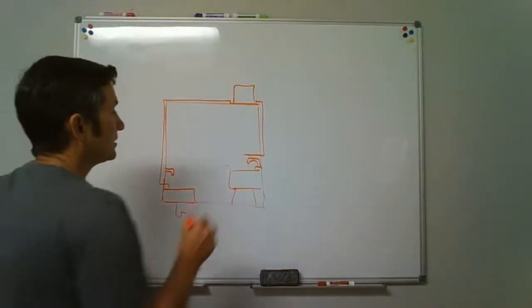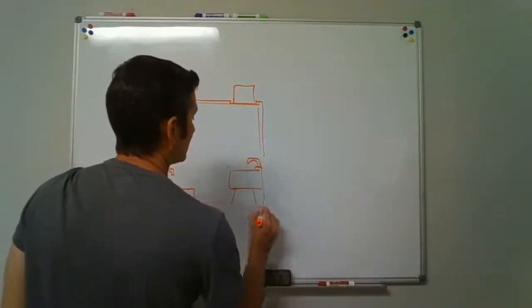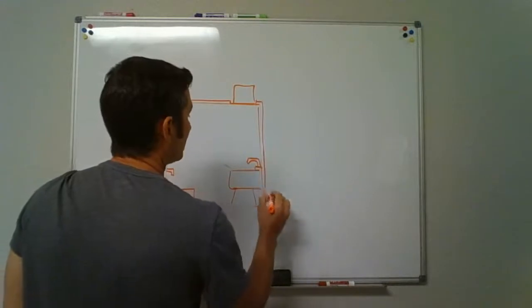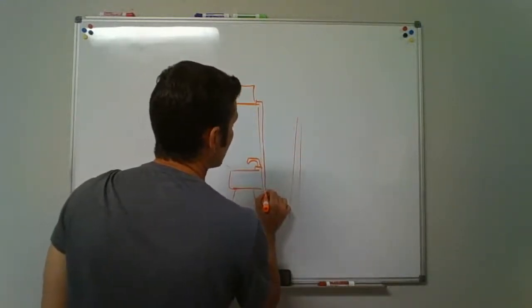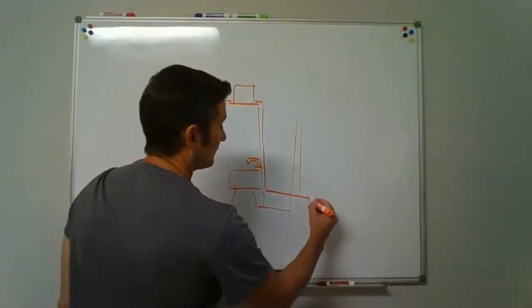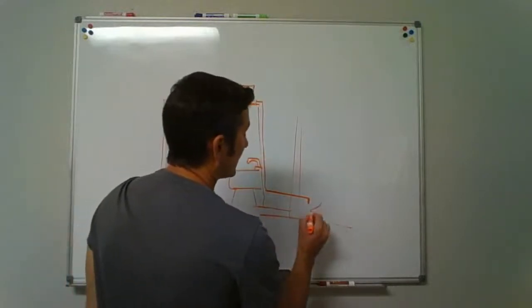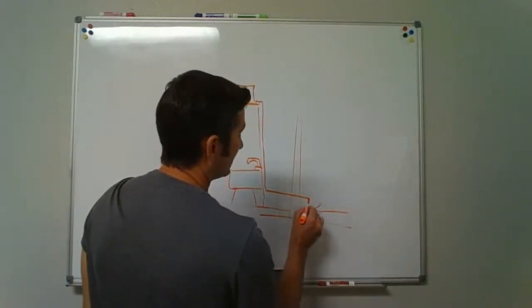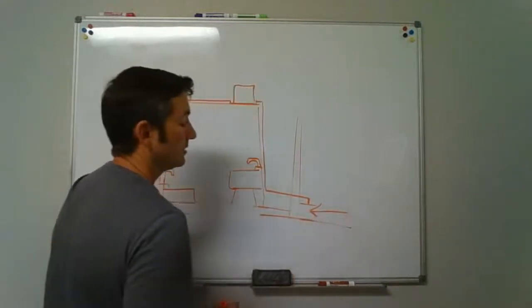That's a location. Another possible location is, if this was exterior, let's just say that's the outside wall, it comes down and it discharges. You don't want to let it discharge horizontal. Turn it off vertical. And that was this gap here between the end of this pipe and the ground.